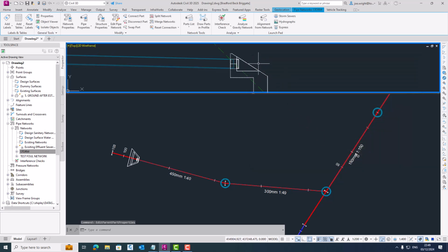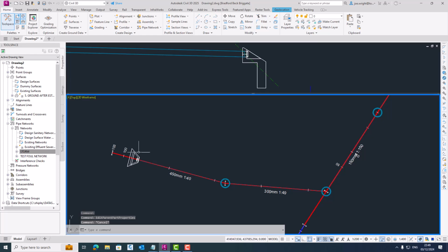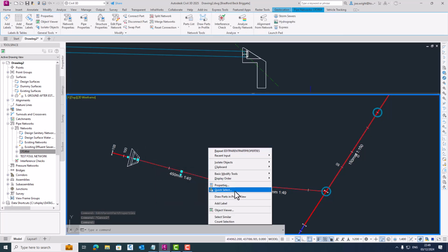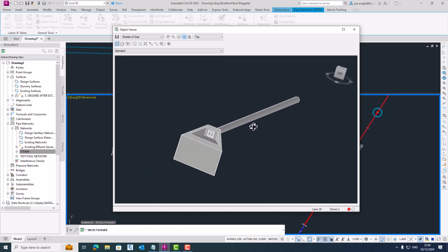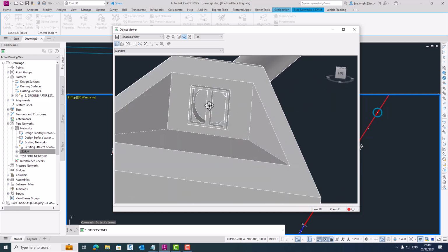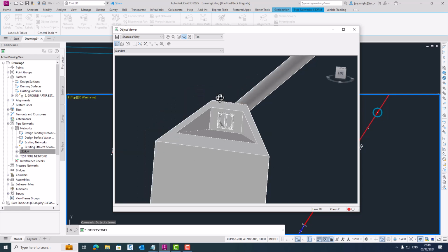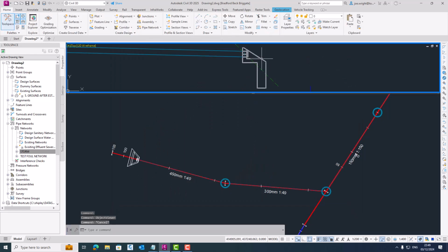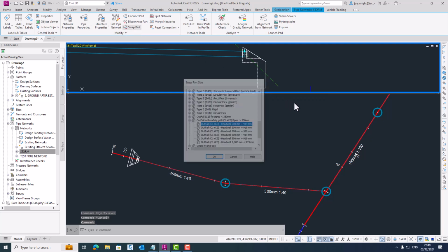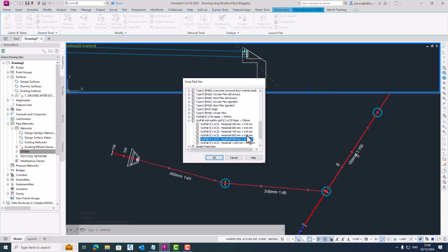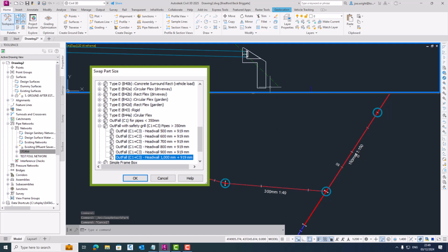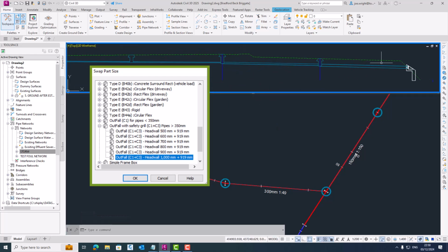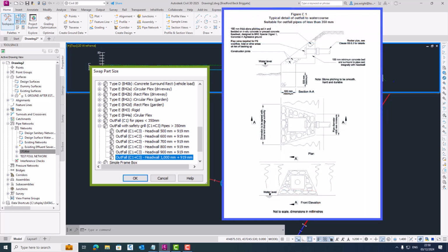The default for this outfall is 919mm, so for an absolutely spot on 3D model, it will need to be changed to match that of the connecting pipe. Done. As you can see, it's now spot on. One final thing, if you want to change the border around the outlet, you will need to swap out the part. Check the specification in design and construction guidance. It says it needs to be 500mm larger than the pipe, at a minimum, and our model can increase this up to 1 metre.